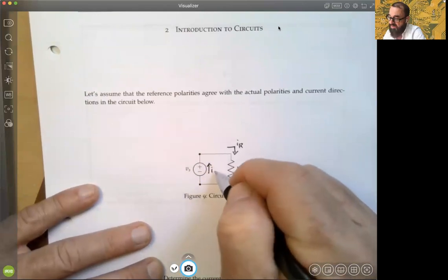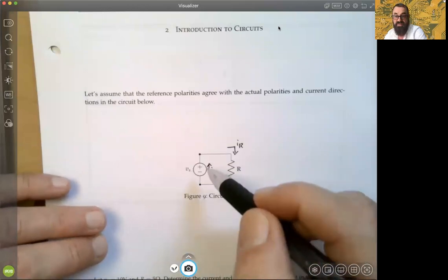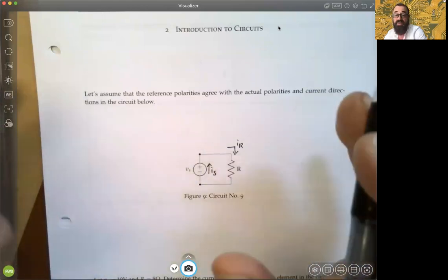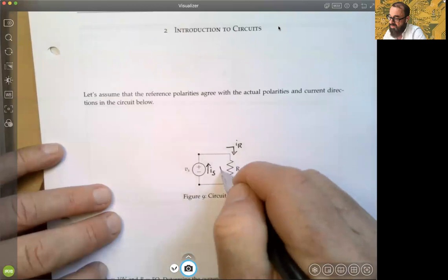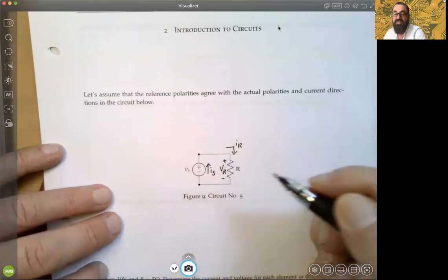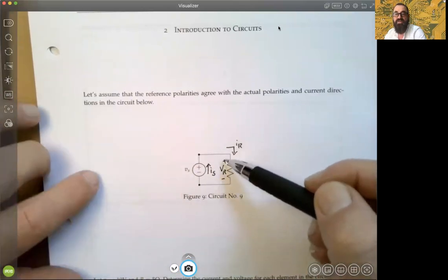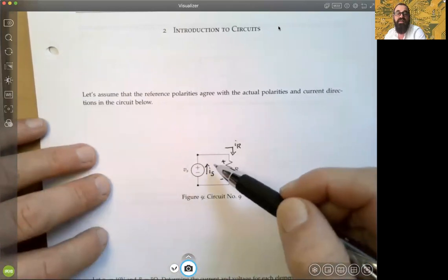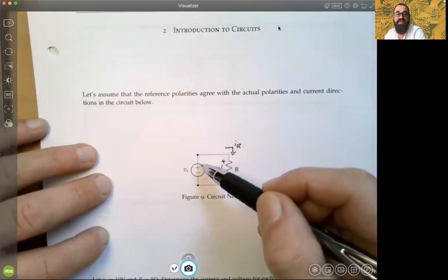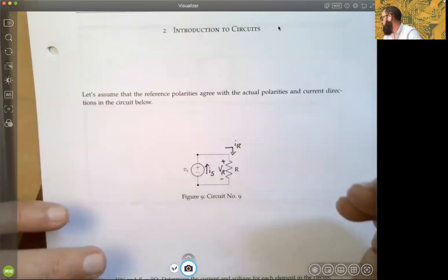So I'll indicate it as I sub S, just for source, right? Now, I call myself for a second, well, these are not in series. They are connected end to end. They are in parallel, okay? So even though I'm going to represent the voltage here, voltage R, plus and minus, notice that because they're in parallel, I'm going to make their voltage polarities agree. In other words, it's typically a good convention to do that. If these two components are in parallel, if the top node is the positive, then I'll make the top node positive on the resistance as well, all right?